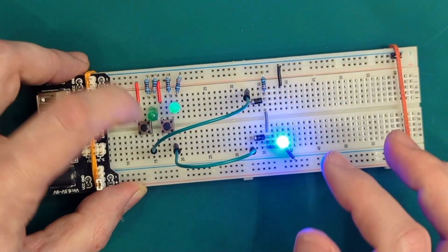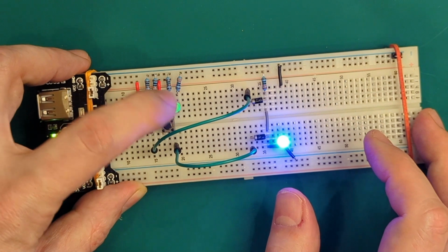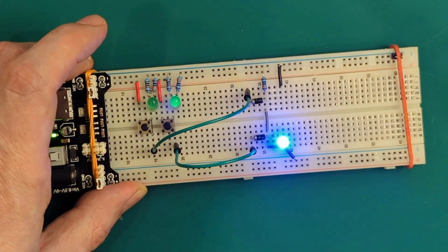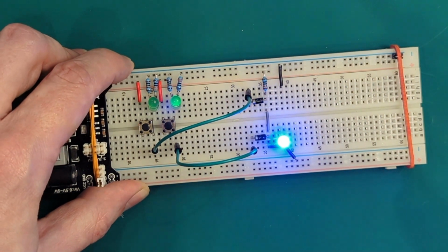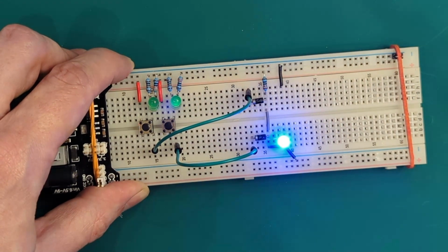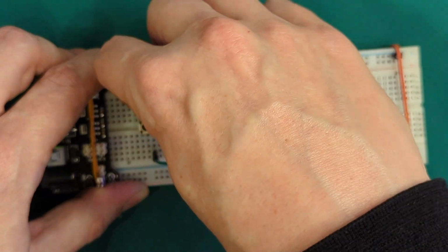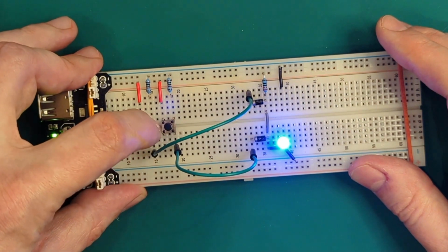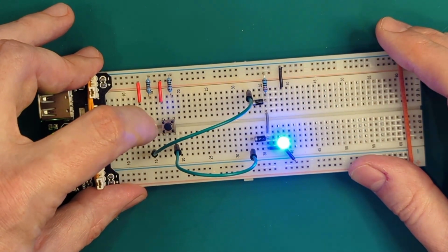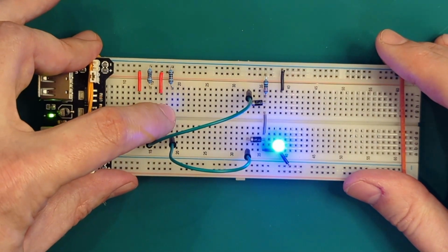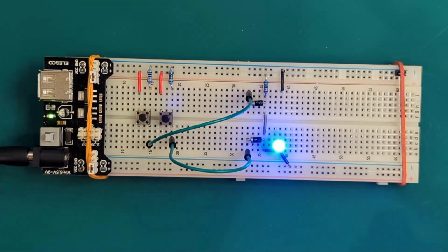Okay, so there's something weird going on. So perhaps you can see that my green LEDs are actually flickering a little bit. And that's actually because, as we mentioned before, this gate is a bit strange because the inputs are actually sending current. So the current is lighting my LEDs. So my LEDs won't help much. Let me remove them. Now I still have two buttons and it still doesn't work. So you can see if I press the button, the glow increases a tiny bit, but it's still on in this case where it should be off. There's something very wrong going on here.